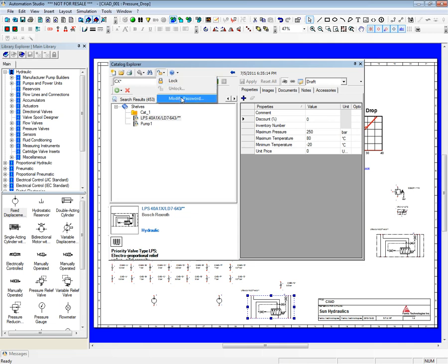So there may be just a team that could define your own catalog, and then all of the rest of your company can use it and won't have the ability to make changes on it. And when you include components, you could even put the unit price of these components within your catalog. And then that could be part of your bill of material. With the bill of material, you have the ability to sum all of the prices on the diagram, so you could easily know how much it would cost approximately to build this kind of schematic.